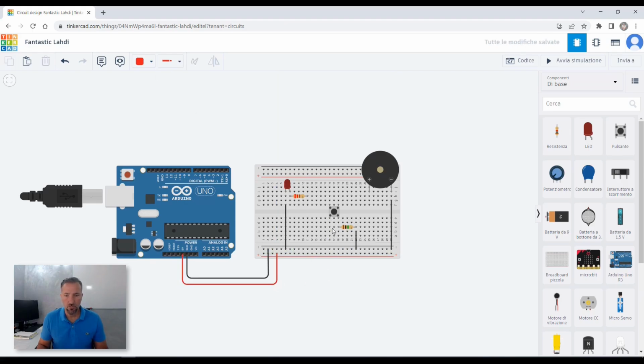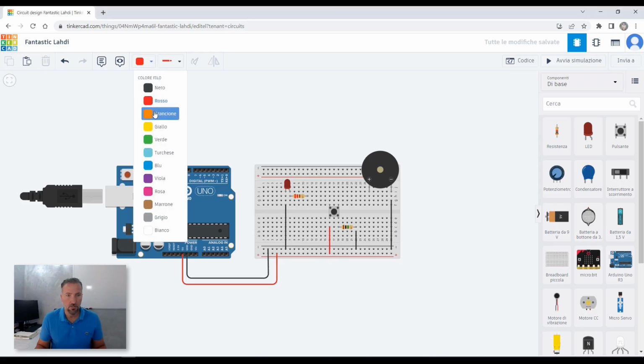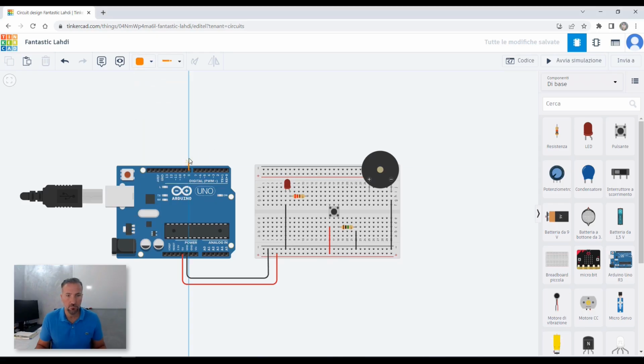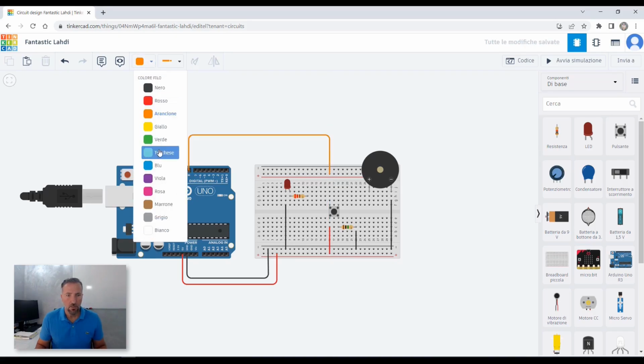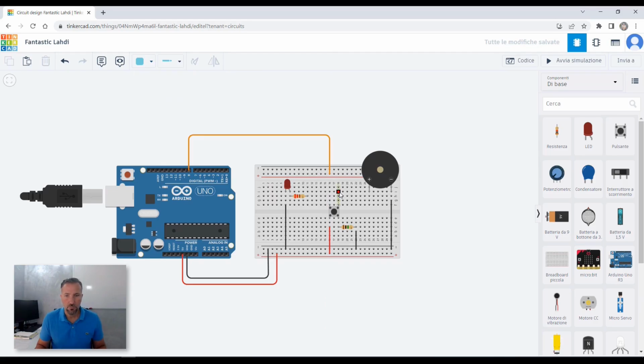And use these 5 volts to have a high voltage from one side of the button, which we will then transfer to Arduino to communicate that we want to turn on the LED and thus the buzzer. We decide on 2 pins to power the buzzer and LED simultaneously. So for example, we can use pin number 8 and carefully bring this state to the red line at the top part of the breadboard. So we take as the button input the pin, for example, 7.